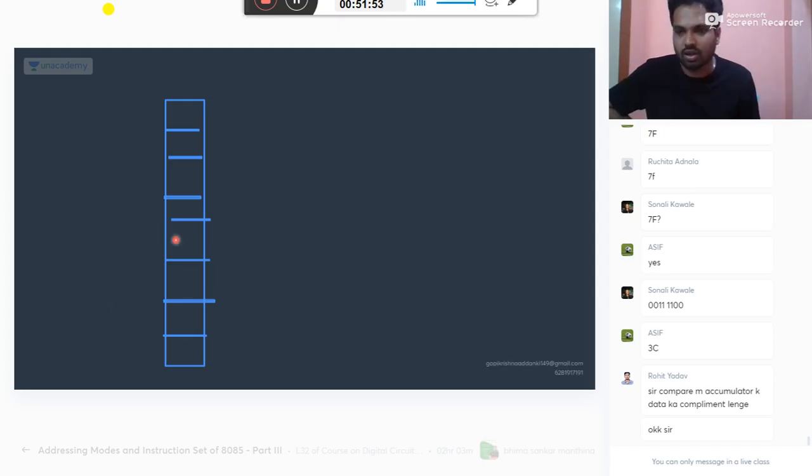During this time, you don't want a few alarms to ring, which are not very important for you. Fire, temperature, those may be important. So for the remaining ones, what you do is an AND operation with 0. Whatever your input may be, AND with 0 will give you 0 only. These alarms will not ring in that case. This is called masking.